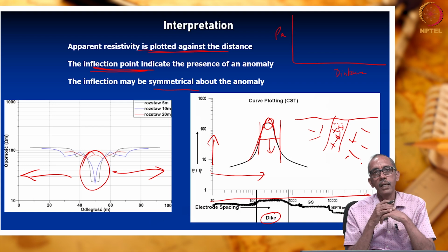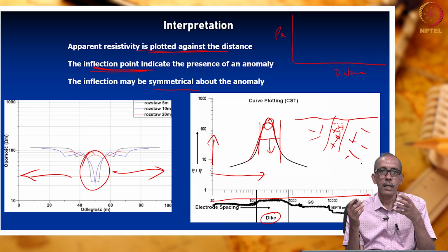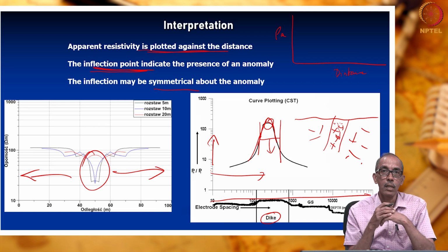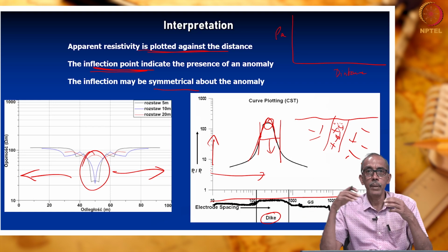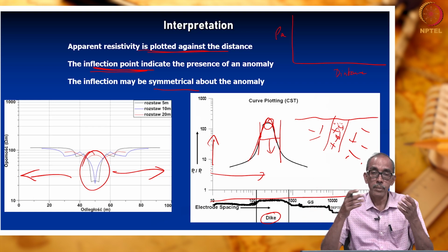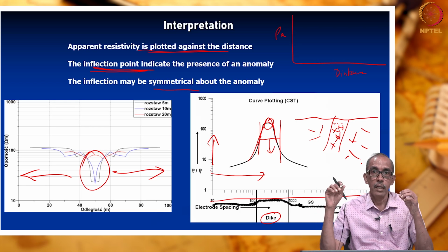So, generally electrical profiling is carried out whenever we need to carry out some projects along a particular line, maybe a bridge or sometimes a dam, or especially roadways, railway lines, or pipeline infrastructure.